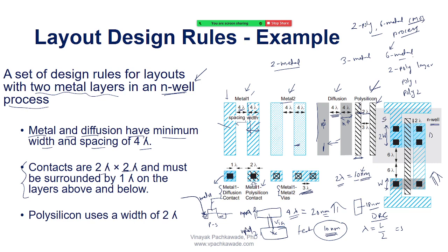This is the source of the PMOS. This is the drain of the PMOS. This is the drain of the NMOS. This is the source of the NMOS. Source is connected to the ground, and I know that drain and drain are connected, so this is output Y. Then I have the N well, and this is the source, connected to VDD. Okay, so I have metal and all this.